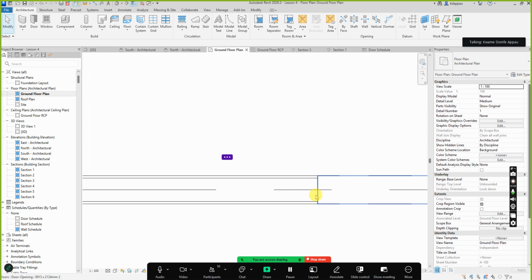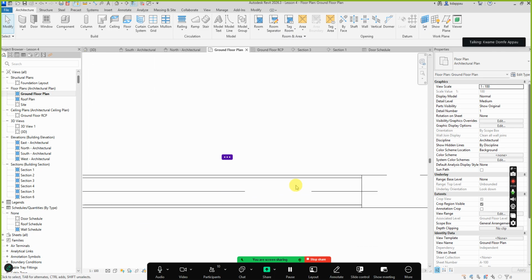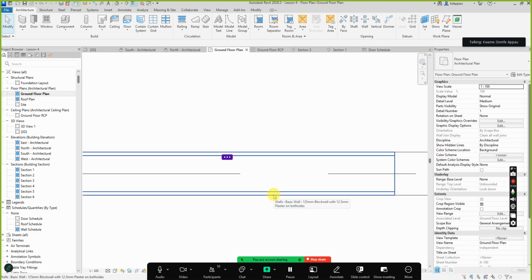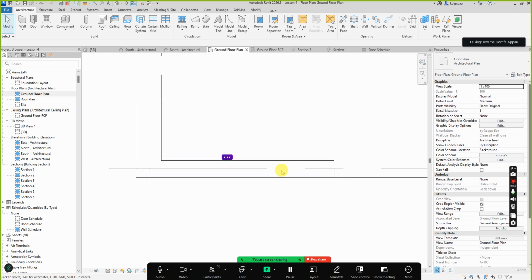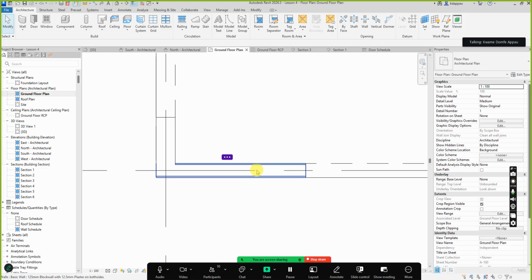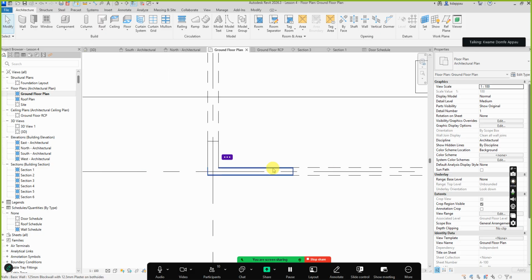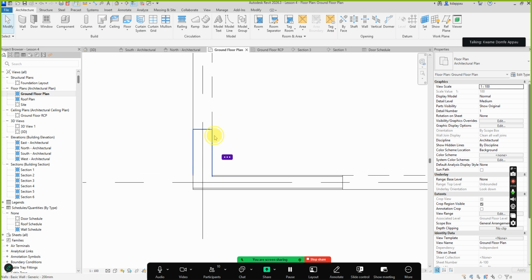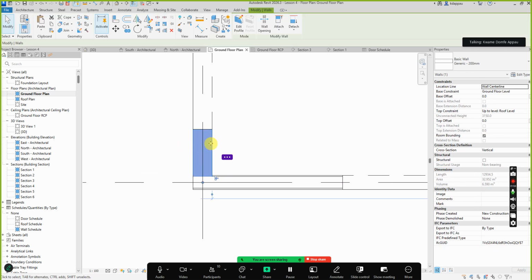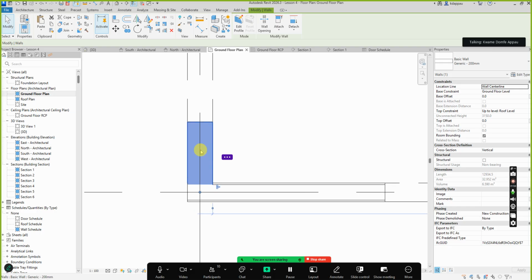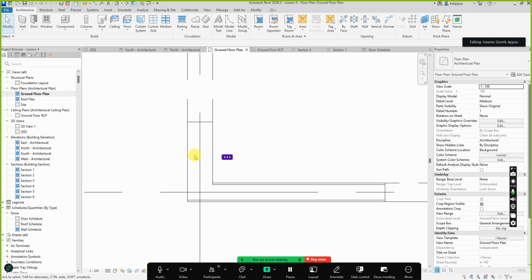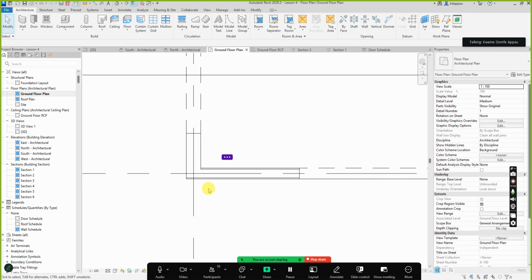If I look at it, there is a plastering on the outside, 12.5 mm. Then there's a plastering on the inside, which is also what? 12.5 mm. Then there's the main structural wall. Construction-wise, this definition of wall that I've created here is more correct than this definition here, which is just a blank wall without any plastering, just a monolithic wall.